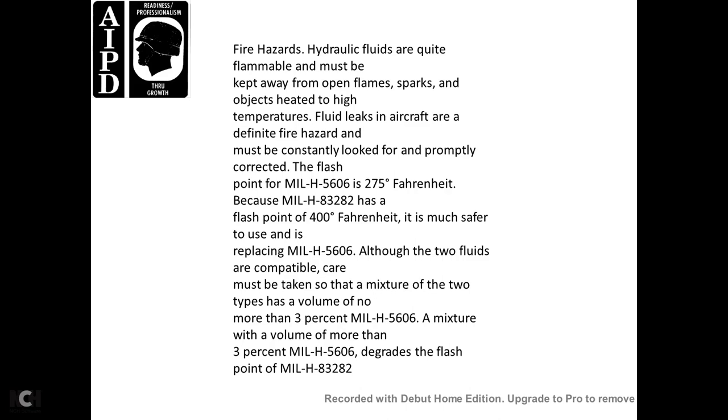Because MIL-H-83282 has a flash point of 400 degrees Fahrenheit, it is safer to use than MIL-H-5606. Although the two fluids are compatible, care must be taken to make sure that the mixture of the two types has a volume of no more than 3% of MIL-H-5606. A mixture with a volume of more than 3% MIL-H-5606 degrades the flash point of MIL-H-83282.